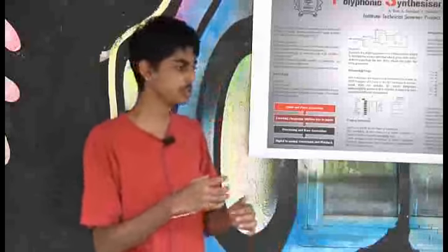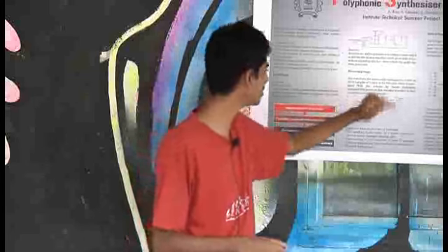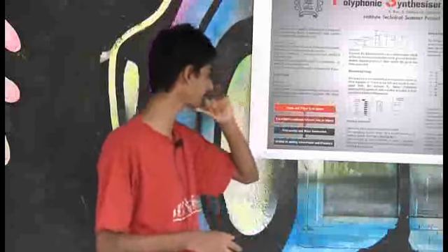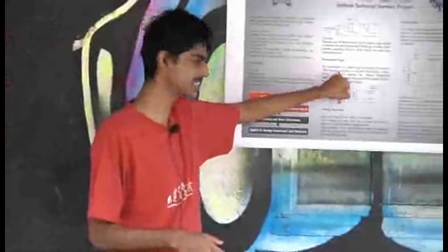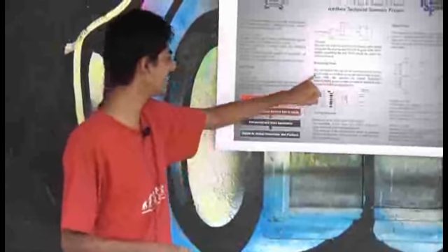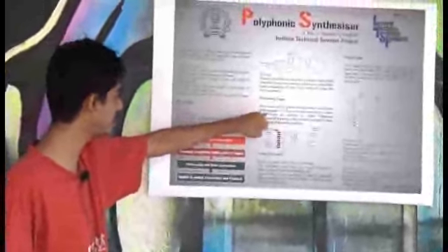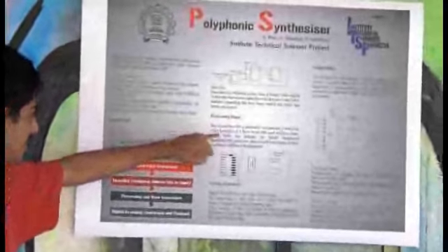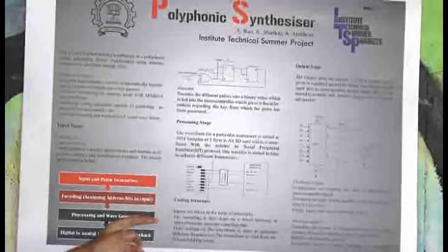Hence, using this sort of algorithm, we have generated frequencies by scaling the waveform. The scaling involves rounding off because the samples are discrete, they are not continuous. However, the inaccuracy is negligible because 1024 samples for one waveform is an extremely high wave density. The next part that we have here is the coding structure.